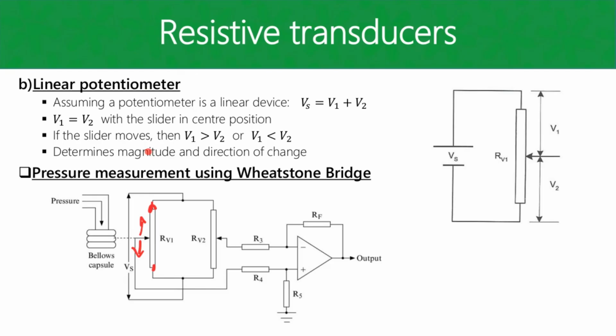Okay, in any case, coming back to the linear potentiometer, this RV2 can be another linear potentiometer which generates your reference, or it can even be a rotating potentiometer, or just two resistors. Essentially, via your changing contacts, you basically have a Wheatstone bridge here.